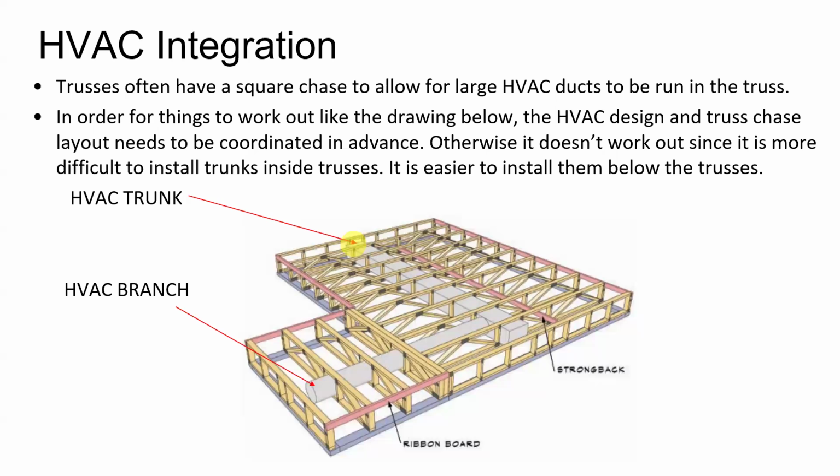So I've seen a lot of jobs where we put floor trusses in and we were hoping that the HVAC, when they came in and did their bid, would be able to run their ducts up into the trusses. And they're like, yeah, we can do that, but it's an extra X $1,000 because it's so much easier for us to just make them, screw them to the underside and be done with it.